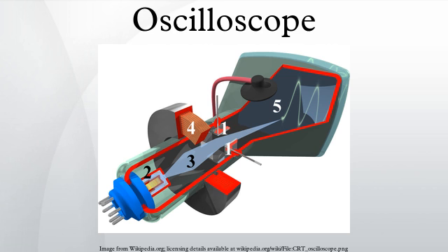They have a few frequency ranges, and relatively wide-range continuous frequency control within a given range. In use, the sweep frequency is set to slightly lower than some submultiple of the input frequency, to display typically at least 2 cycles of the input signal. A very simple control feeds an adjustable amount of the vertical signal to the sweep oscillator. The signal triggers beam blanking and a sweep retrace sooner than it would occur free running, and the display becomes stable.